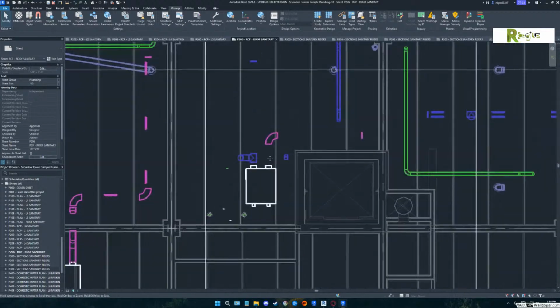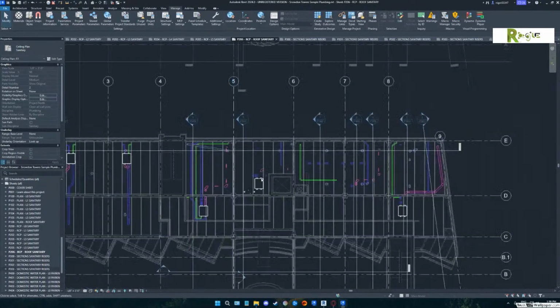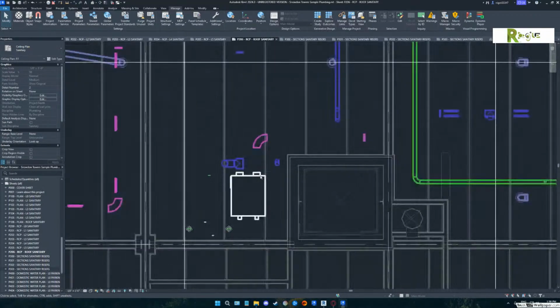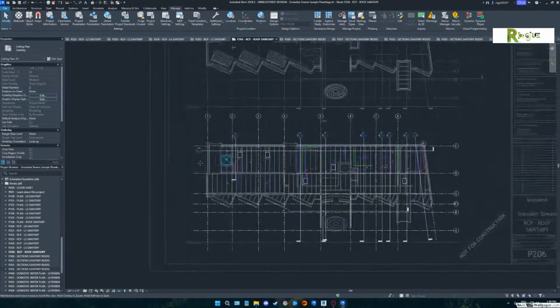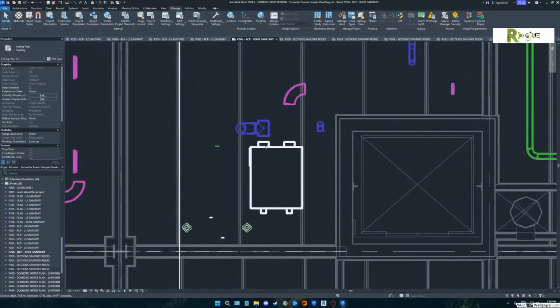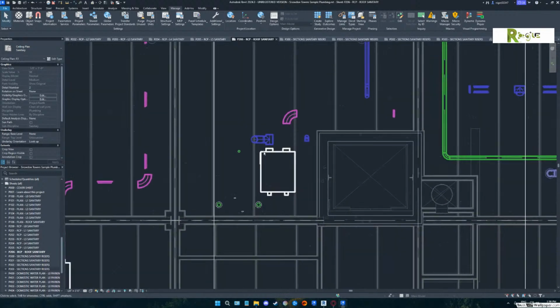What are those white boxes? Double click to get into view. All right, pick on it. Can you? Oh, I am. I am in a view. Yeah, now pick on that white object. If you can't pick it, that means it's coming from a linked object. So you need to do the select links.